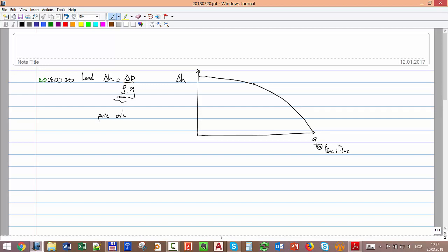Let's say that you're operating here. If you had pure oil, the density of the oil is maybe around 790, and the delta P will be the delta H at that point times 790. But if you have pure water, then you have the density, let's say, something like 1024.